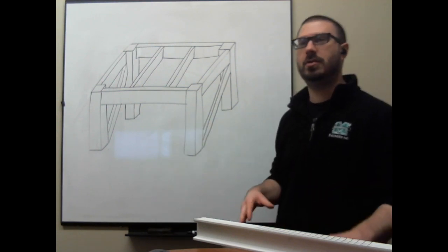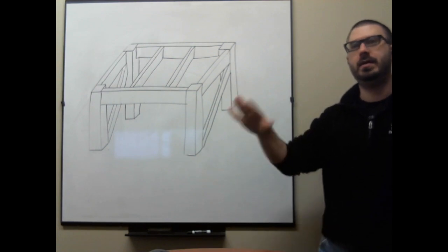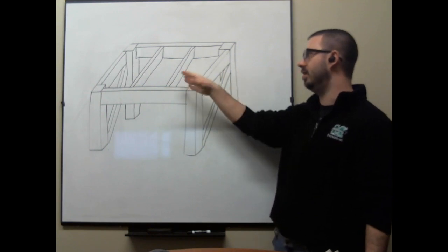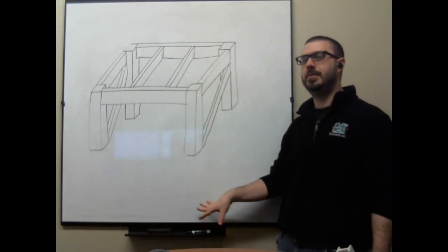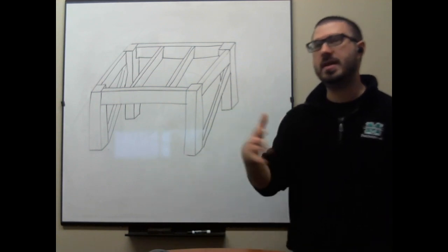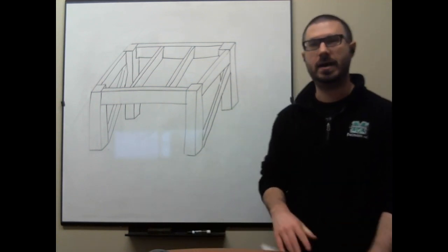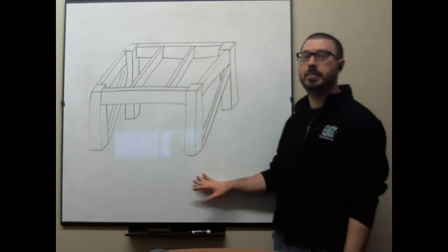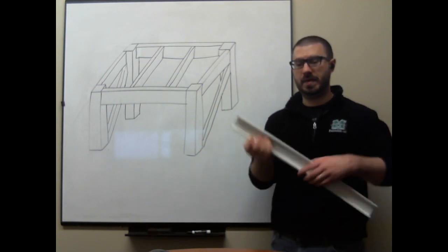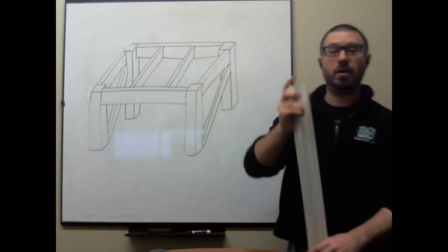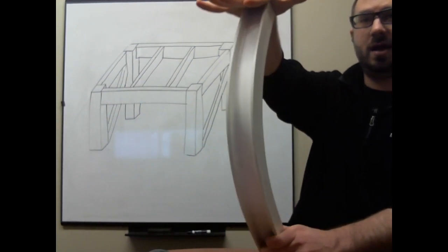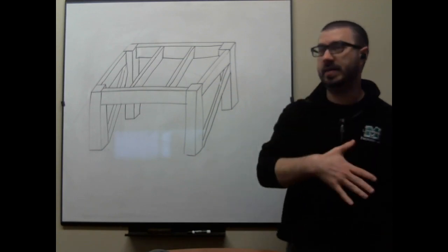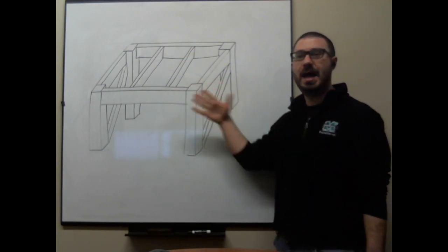But what I have here is a conceptual view of a framing plan of a building. It's a really simple framing plan. There are just 4 columns and a few beams and whatnot. But this framing plan really does demonstrate everything that you would find in a building like this. There are really four main elements that go into a framing plan like this. There are the beams, the elements that are designed to be bent. There are the columns that are pushed down and want to act like this. There are the connections, either bolted or welded, that connect elements together.